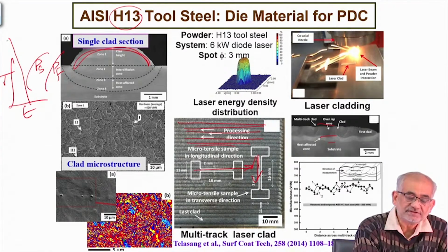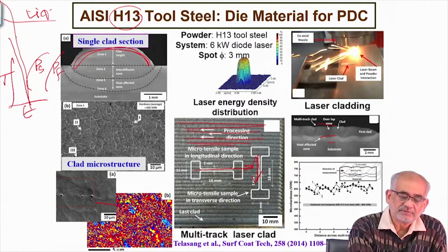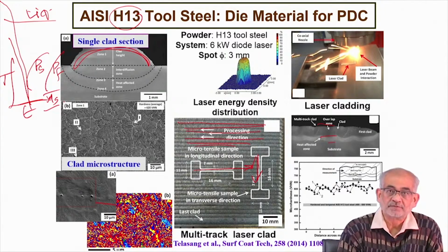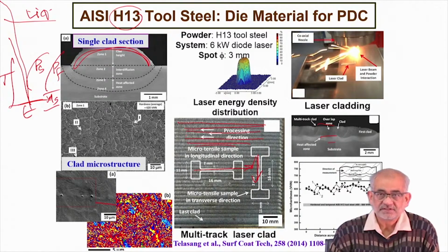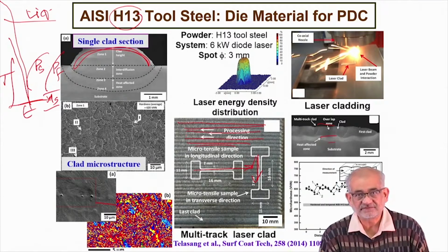Now, usually this is a solid state process, but when you start cooling all the way from liquid state, so here is your liquidus line, you start all the way from liquid state to be able to avoid altogether and then reach room temperature after crossing the martensite start. This is not very commonplace. But in this kind of a situation, the bulk of the substrate acts as a heat sink and extracts heat very fast.